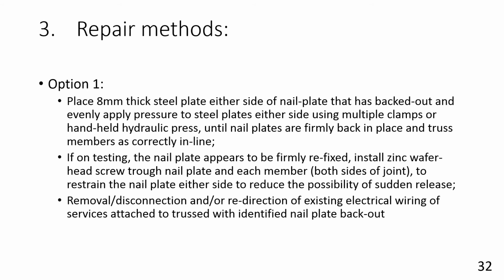Nail plate backout could be addressed by using a couple of methods. The first, option one, is by repressing the backed out nail plates to their original factory impressed position and then providing screw fixings to retard future nail plate backout.